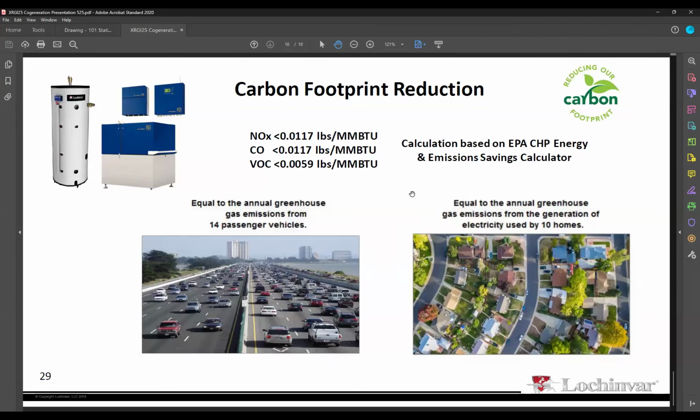If something has to be instantaneous, then its generation has to be significantly greater, because you don't have any storage. Like we were saying before, you'd have a 12 kW, so 40,000 BTU heat pump with a 2,000 gallon tank supporting a building, or you'd require 800,000 BTUs and no storage if it's instantaneous. So everybody's shifting to volume to shrink the heat pump and reduce cost. So instantaneous wouldn't even make sense.